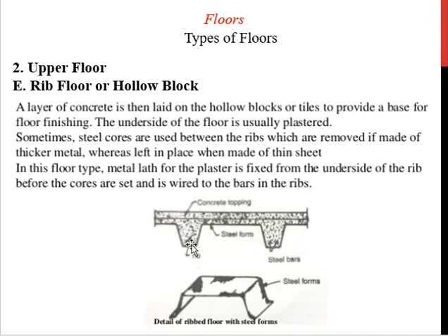So we have not just removed a certain section, but we have formed a hollow section on the basis of the calculation that below this section there will be a hollow section, and there will be no tensile value, only shear value. Again, these are things from a calculation point of view. When you calculate the neutral axis, you will get an idea of how much height the steel form should be. If you study RCC, there you will study the T beam, where the neutral axis is, above the neutral axis, below the neutral axis, and depending upon that we calculate the bending, shear and everything. So you will study all these things in RCC.